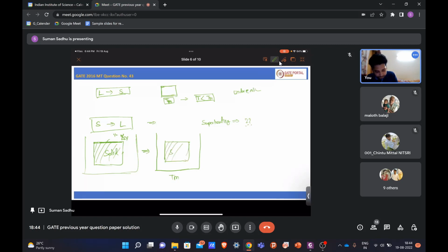So this is solid and a liquid layer is formed, right? For the liquid layer, it will create a liquid-vapor interface with energy gamma LV, and another interface, the solid-liquid interface, which will also have some energy, gamma SL. So basically you are breaking the gamma SV interface, and creating two new interfaces, gamma LV and gamma SL.